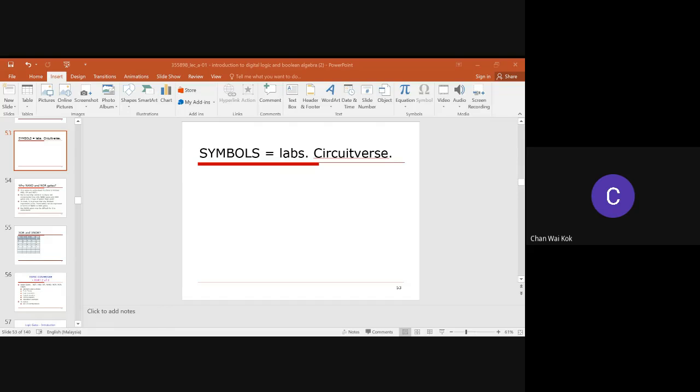Because you might have function 1. Function 1, you use 100 OR gates, one AND gate. Then function 2, there are 100 AND gates, one NOT gate. How are you going to optimize? So what you're going to do, you just design the chip to have all NAND gates. Then you express the function in terms of NAND. All right. Okay, clear.